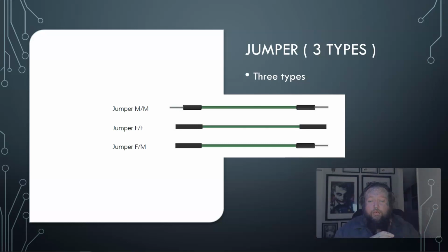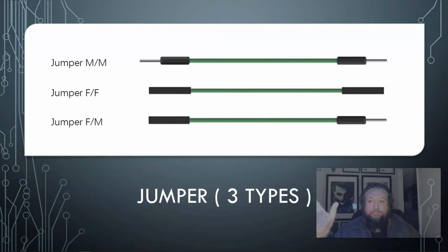It depends upon what you're working with and how you set things up, trying to make that metal to metal conductive connection. But you have to worry about these wires when you're working with them, so be careful bending them, because this is fine, but if you go too hard here, it's going to snap something internally, and you may not see it. This hard piece of metal is connected to the braided metal that's inside here, and if that breaks, we're getting an open circuit and it's not working. So it may physically look like you've plugged it in properly, but internally something could have actually been broken. Woo! Lots of fun there.